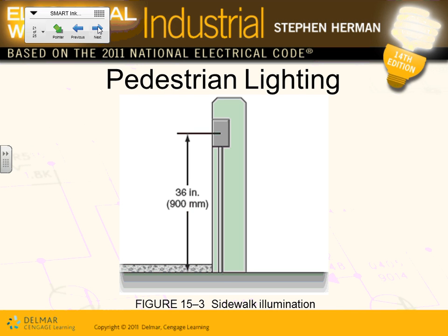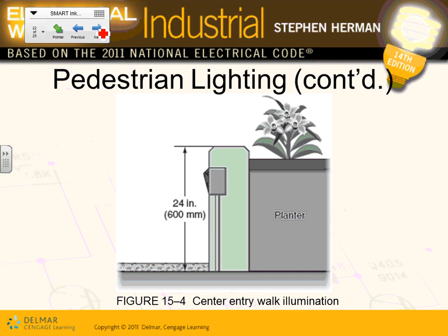Then pedestrian lights, guys. Here's a couple of recommendations. If this is a sidewalk, typically you put your light here with PVC conduit, 56 inches, and it will throw some light up to, I don't know, probably 3 feet. This will throw light for your pedestrian. That's one way of doing a pedestrian light. We didn't do that one.